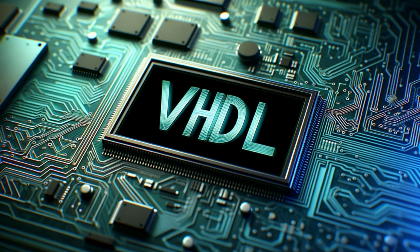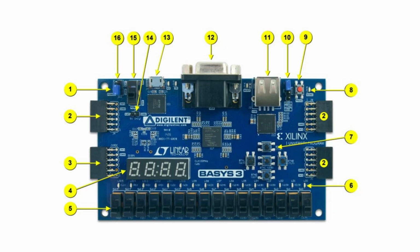VHDL is the programming language that describes the hardware on the FPGA board, and it stands for Very High Speed Integrated Circuits Hardware Description Language. BASYS3 is the FPGA board chosen for this project. It has USB ports, switches, LEDs, and PMOD ports both for digital and XADC signals, as well as a 12-bit VGA output.